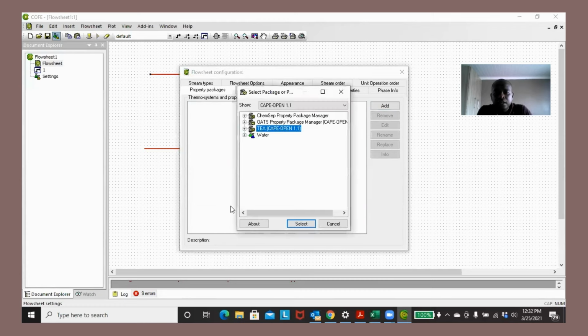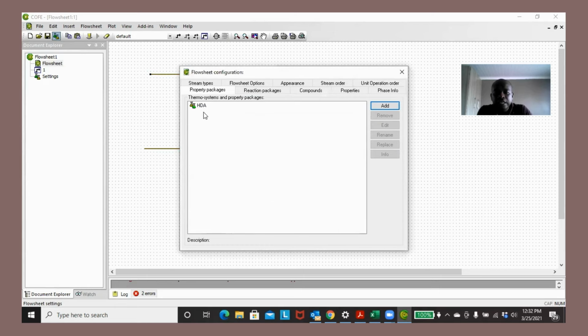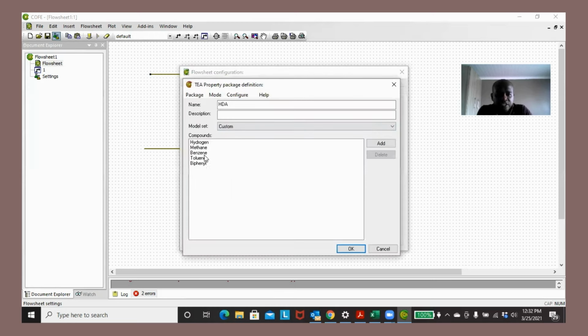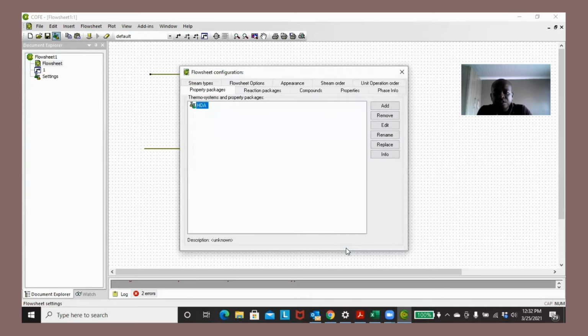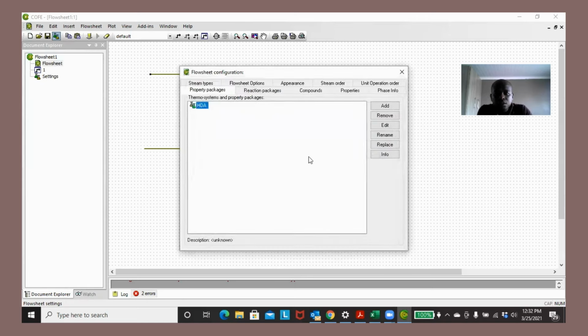Let's go Add again, and again TEA. Let's look at HDA, and then we go Select. And HDA, what do you have in store for us? It's got hydrogen, methane, benzene, toluene, and biphenyl. Let's go with that, just for interest's sake. So we've got those compounds: hydrogen, methane, benzene, toluene, and biphenyl. Okay, let's close that.